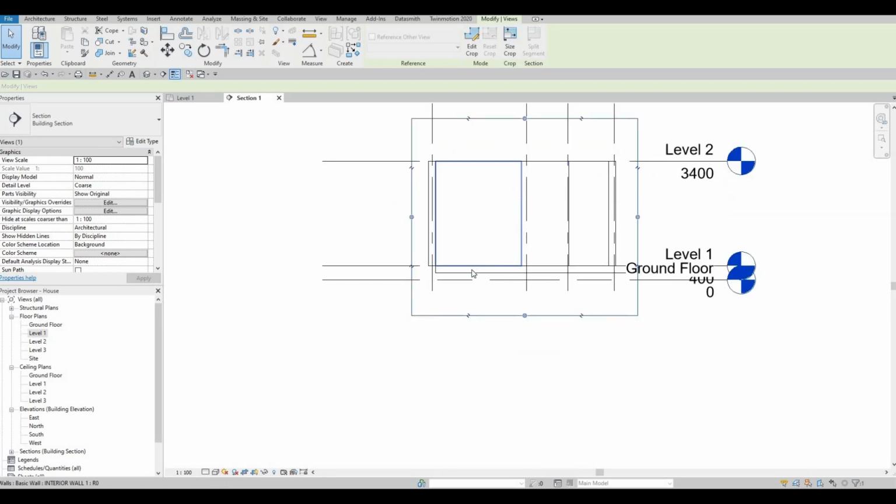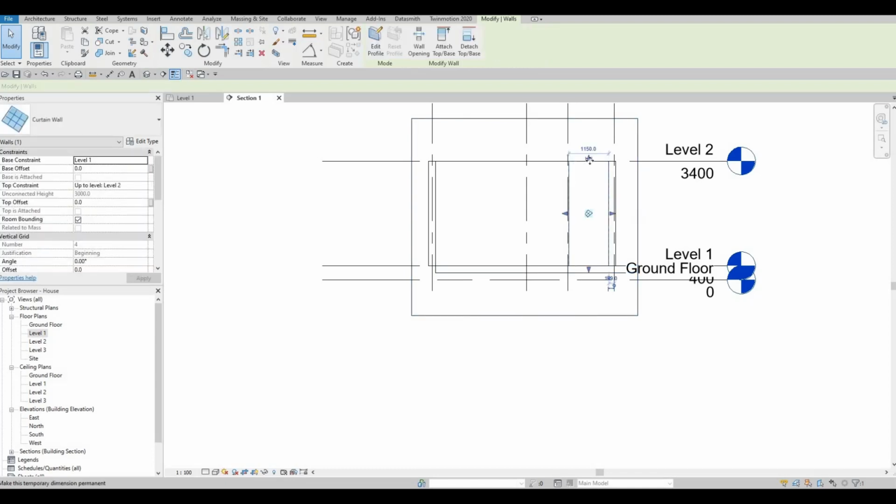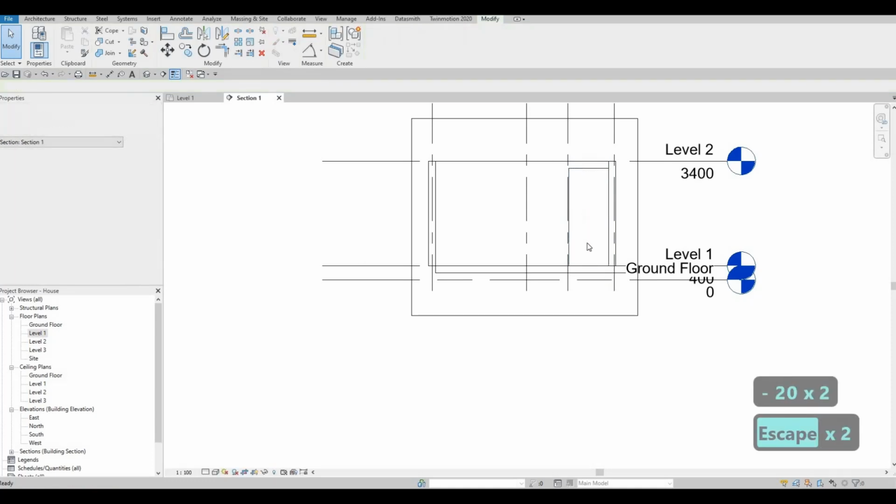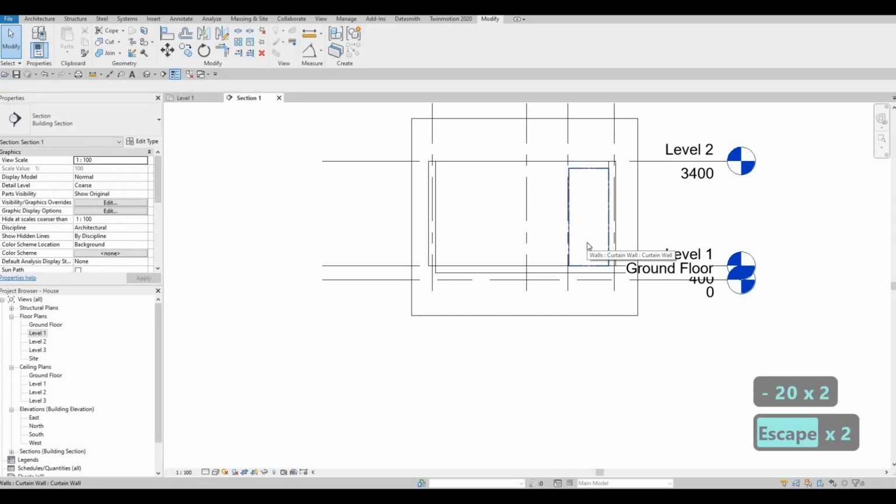And because we're going to add a floor as well right here, we're gonna maximize the height to 2800. So from floor to above, this will be 2800, because we're gonna minus the floor that we're gonna add onto our second floor on our level 2. So here we need to drop this down. So here we can select this and minus 200. So that's the floor to ceiling for that part right there.